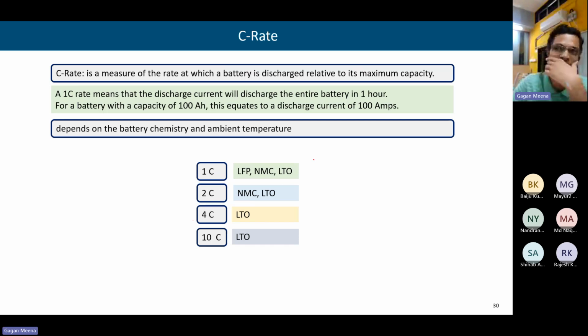Because if you see the Tata Nexon, if we charge it at home using our simple 15, 6 ampere socket, then it will take around 15 hours. But if we have an onboard wall mounted charger, some Mahindra provides one wall mounted charger of around 7.5 kilowatt or something, then the charging time reduces by half. Within 7 to 8 hours, you can charge it.